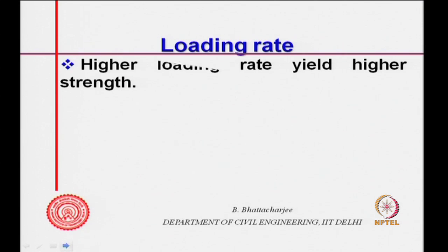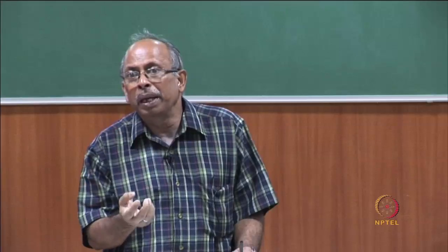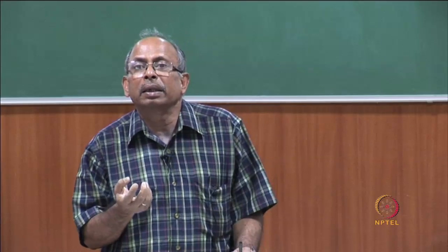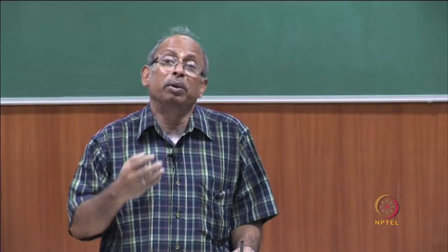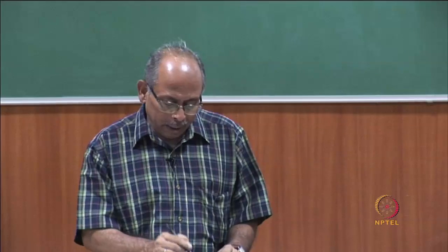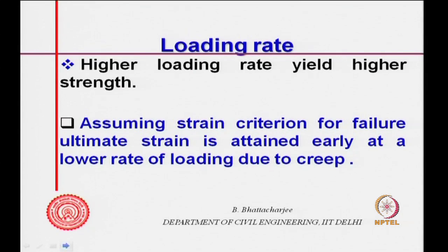Then the next important thing is the rate of loading. A higher loading rate yields higher strength. If you load it quickly, at a very fast pace, the fracture does not propagate so easily; it takes time. While if you just put a sustained load, there will be the effect of creep in an extreme case, so some deformation might occur with time. If you are monotonically increasing the load at a very slow pace, the strength observed will be less compared to doing it at a fast rate. So, loading rate is also important, and many people seem to miss it.